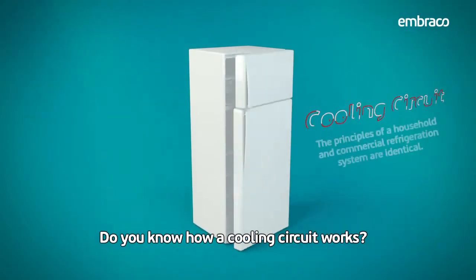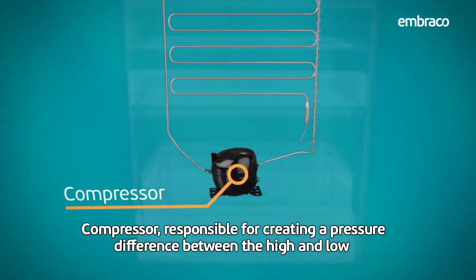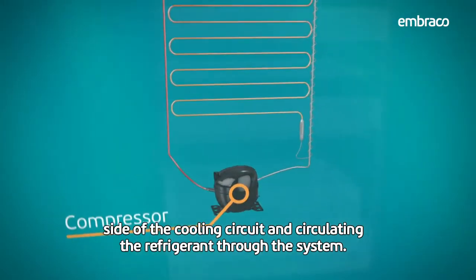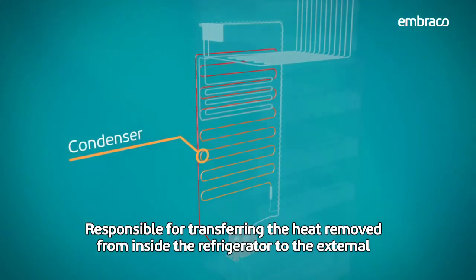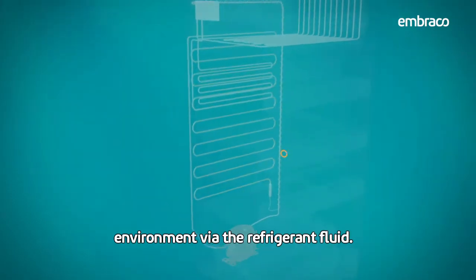Do you know how a cooling circuit works? The refrigeration system consists of compressor, responsible for creating a pressure difference between the high and low side of the cooling circuit and circulating the refrigerant through the system. Condenser, responsible for transferring the heat removed from inside the refrigerator to the external environment via the refrigerant fluid.